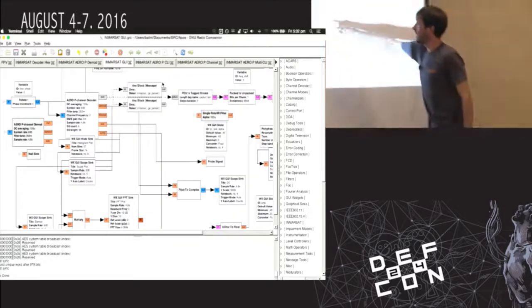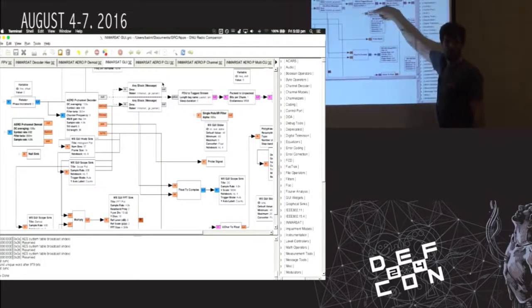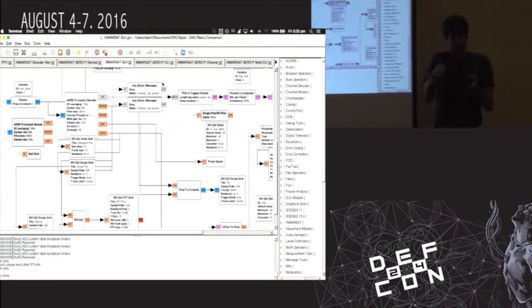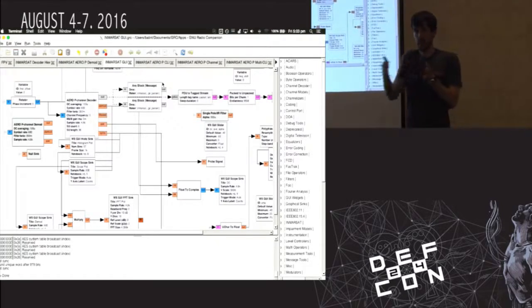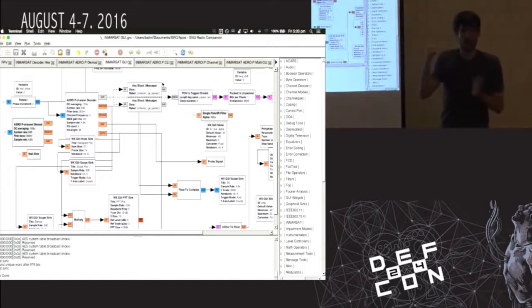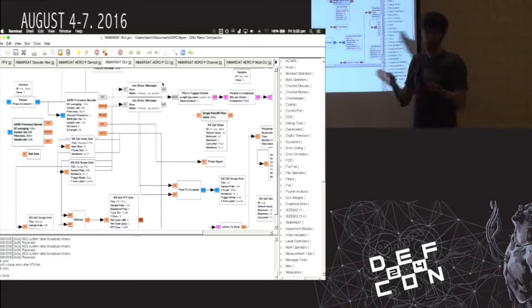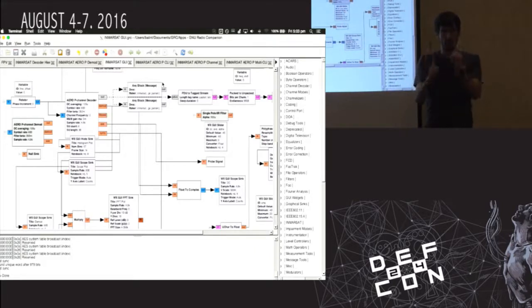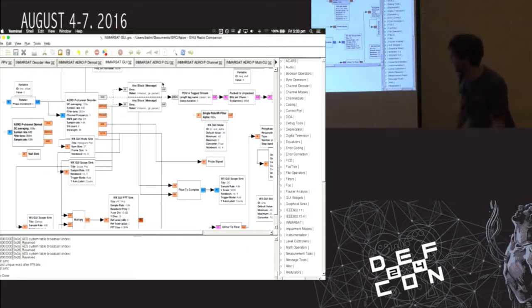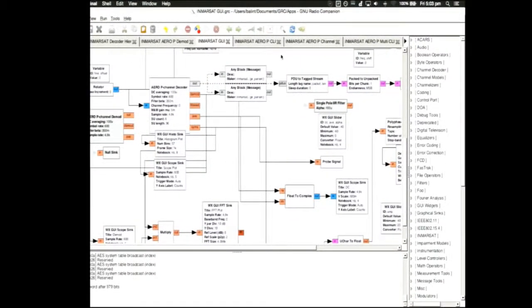Did you see how it sort of found it and there were bumps in it? Those are the sorts of frequency offsets that you can sometimes encounter, larger than you might expect, which is why you need this setup to do that fine frequency correction. Remember, our two symbol points are only 300 kilohertz, in this case normalized, either side of the DC. If you have some massive frequency shift, even just temporary, it's going to corrupt your data because you'll have all ones or all zeros. So let's do them all at once.